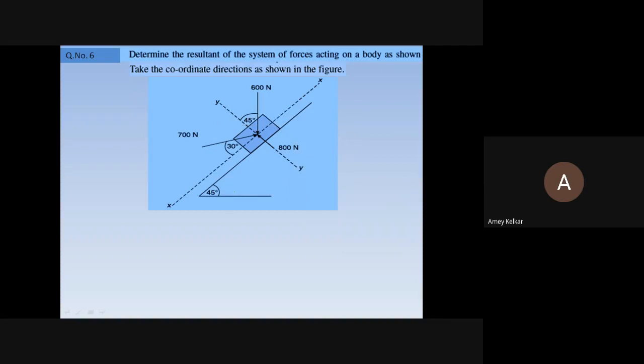Now, one hint you've got to remember always. This angle of the slope and the angle made by the vertical force. Self weight will be acting vertically downwards always. The angle of this slope and the angle made by this force with the vertical axis will always be the same. If this is not given also, you have to take it as 45 because the overall inclination is such that whatever angle the slope makes with the horizontal, the vertical force will make that same angle with the vertical. Always remember this, mark this point.